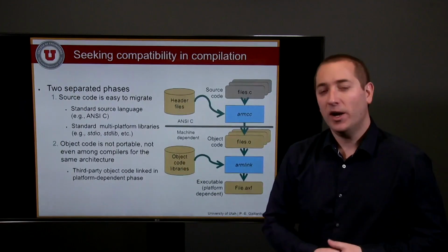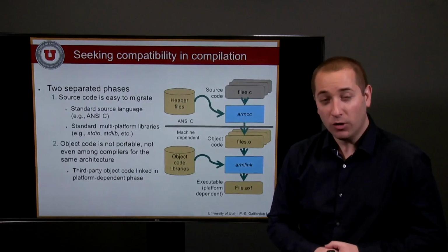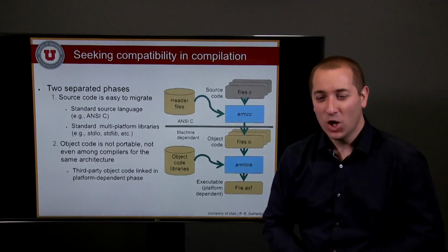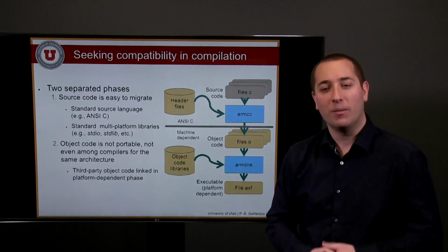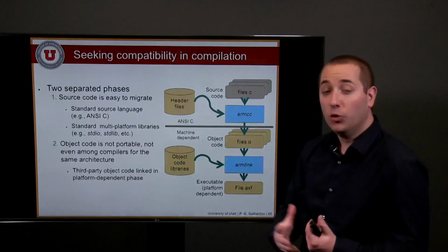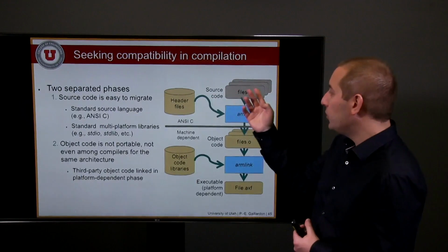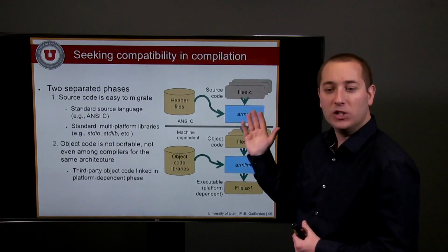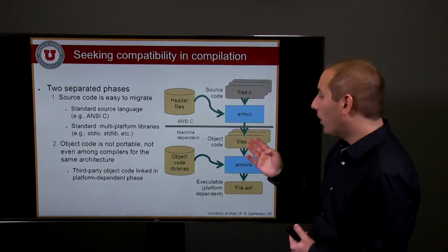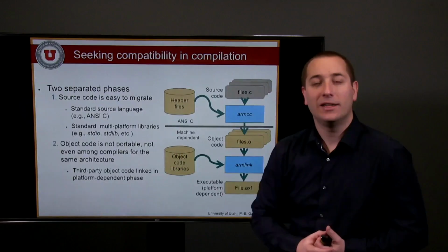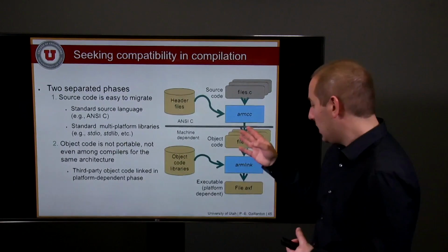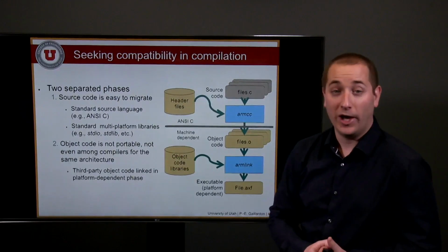Now, something quite interesting in this approach, even though C code is not made to be retargetable very easily, we're still looking for compatibility during the compilation. This is why we always have these two steps: the first step, compiling the C code into object files using the ARMCC, and then the second part dealing with the link as well as the packing into the executable file.